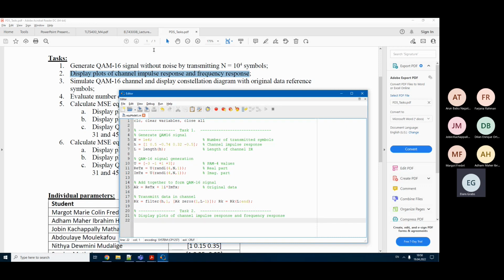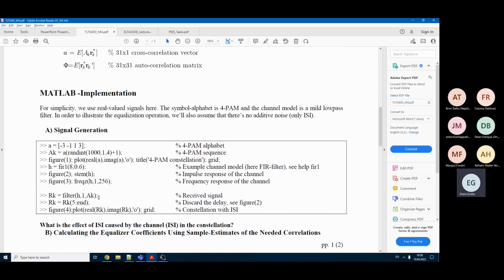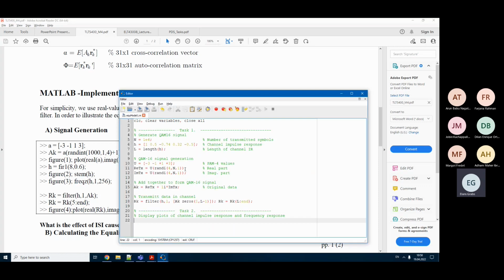So here I'm not going to be quite long in explaining. Yes, also I believe this also has some impulse response system, frequency response is FreqZ. So yes, let us do the same way. The only thing is that we are going to have multiple figure plots, so let us make this as a figure 1. And here we are going to have 2 subplots, subplot 211, subplot 212.